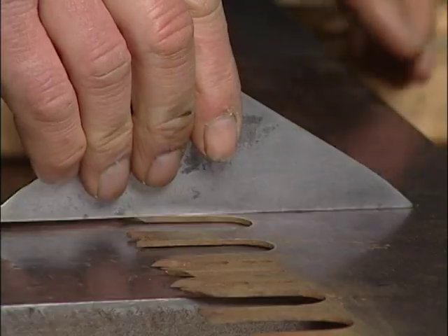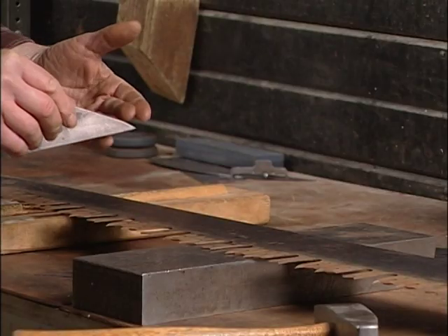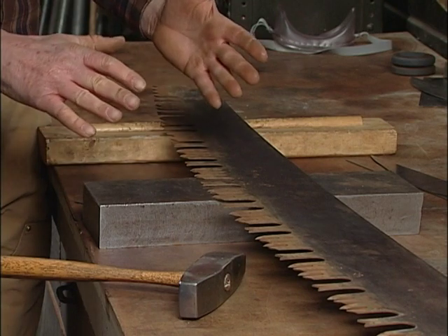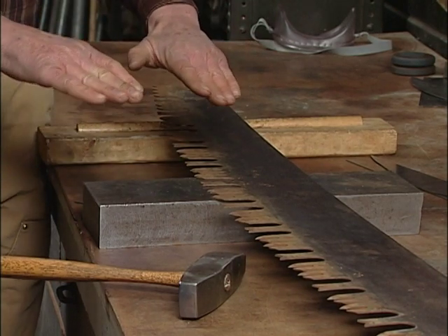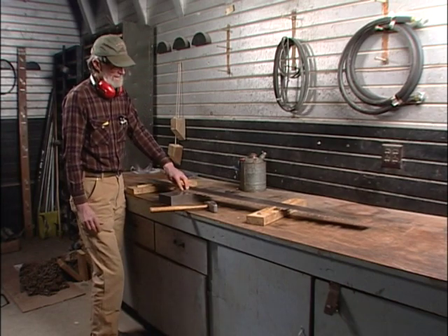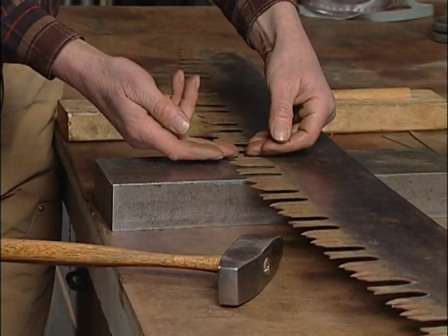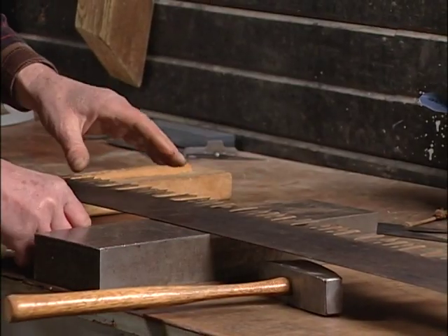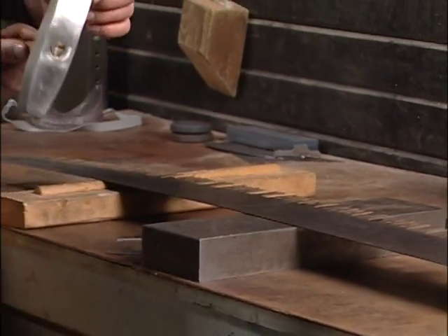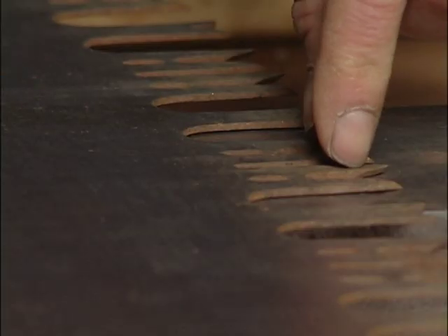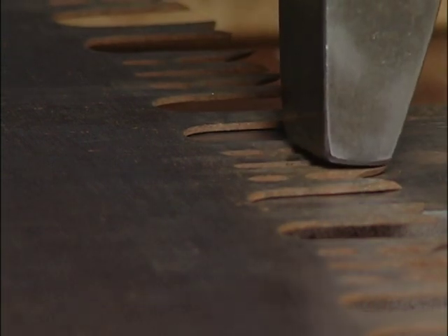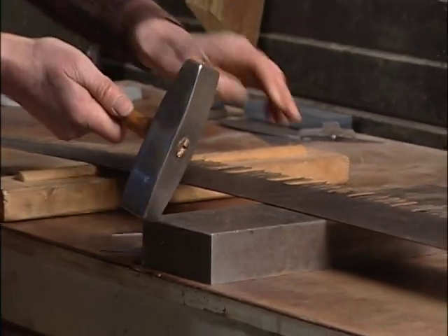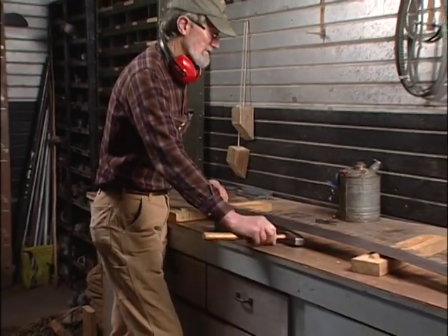And then check it with the straight edge and see what the reaction of the hammer is. And if I had struck it enough to straighten it out, then I'd be done. You use the same procedure if you find that you have a cutter tip that for some reason has gotten bent out of the line. One of the difficulties in using a hammer like this with a very large face in between your teeth, your hammer face is actually wider than the distance between your teeth, so you have to be very careful about using the center of the face to bend that, otherwise you'll end up damaging adjacent teeth.